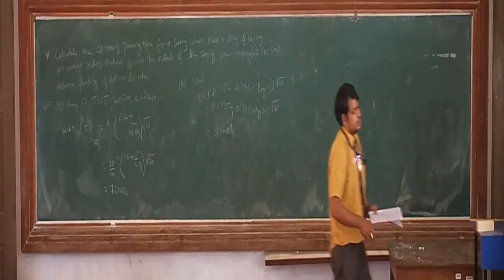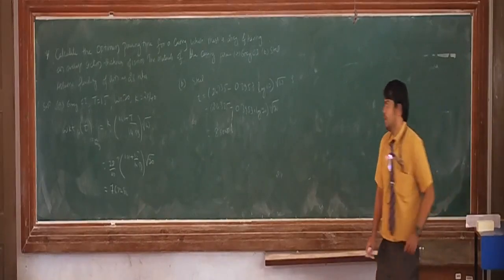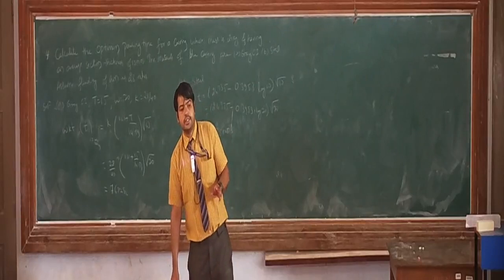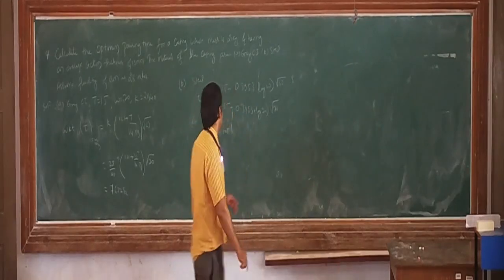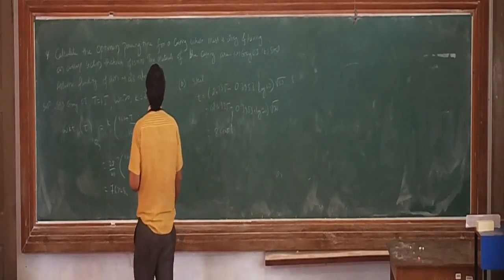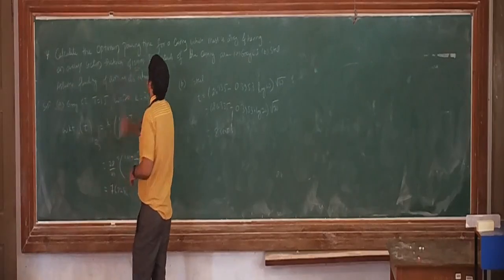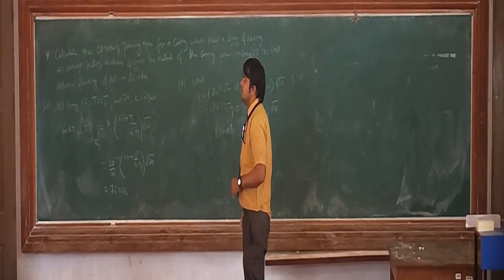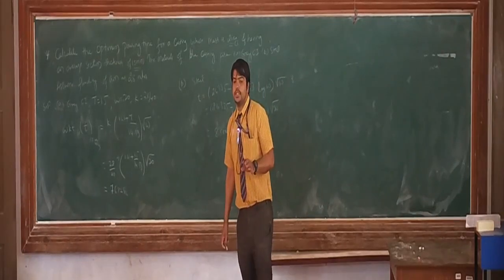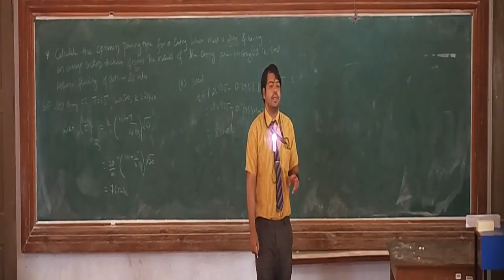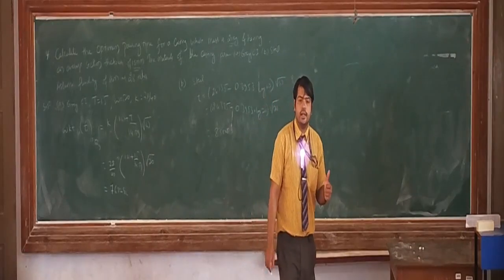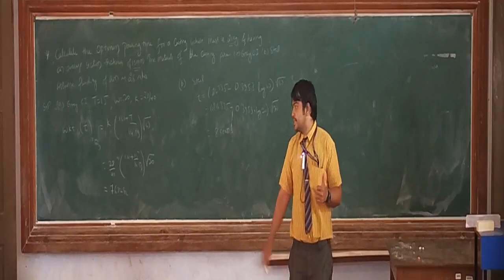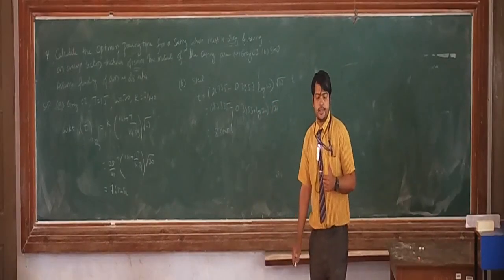Okay, so I'll explain this once again. In the problem, the average section thickness is given as 15 millimeter, that is this particular part. Casting weight is given as 20 kgs, this particular part. And they have told us to find out the pouring time for two metals. One is grey cast iron, another one is steel. The fluidity for the grey cast iron is given as 28 inches.